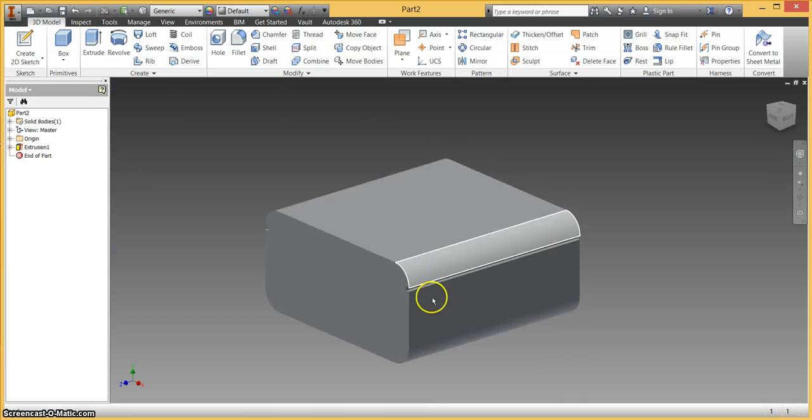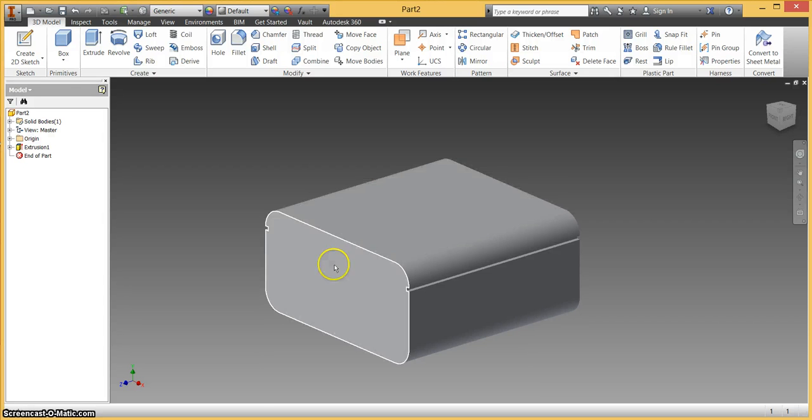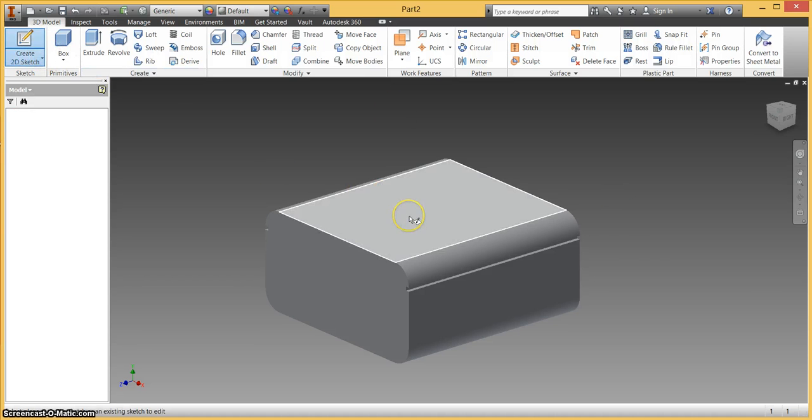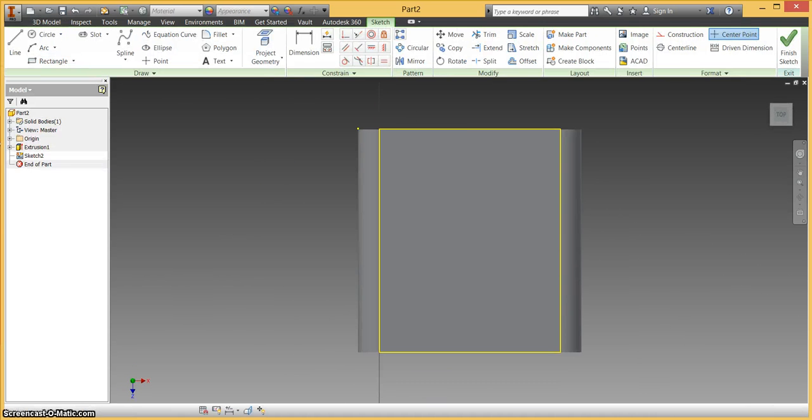Pretty straightforward. I really just need to make a rectangle with fillets, and extrude it. So I'm going to start with the top. Create a sketch on the top of the part. Draw a rectangle on the top of that part. The rectangle in particular, I'll just put some dimensions on it. Looking at the upper drawing on that isometric for my dimensions, 1.98. Enter.